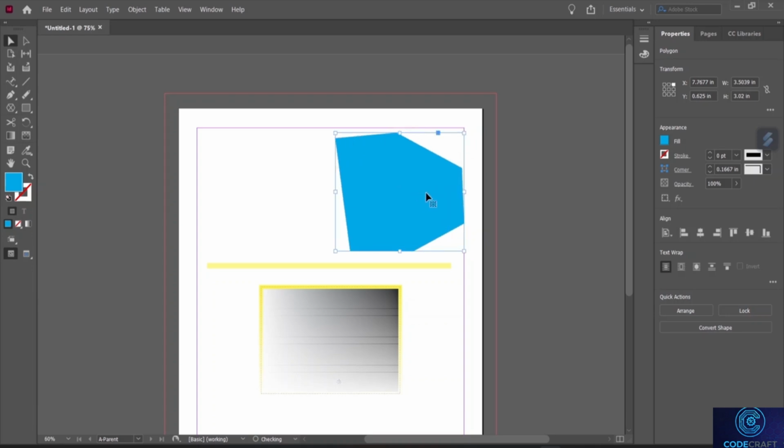And if I want to do it manually, I can do it manually as well. Especially this alignment option is used when we create a particular design and underneath we have text, or we need some type of design which we want to align in a particular shape. Then we can actually use this align option here.